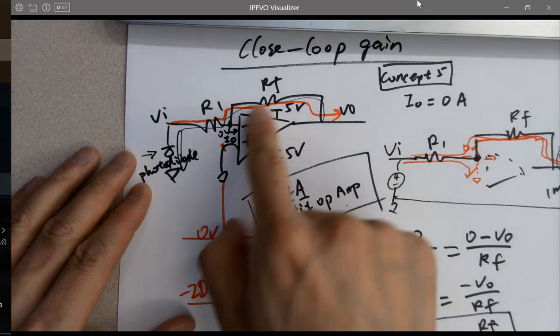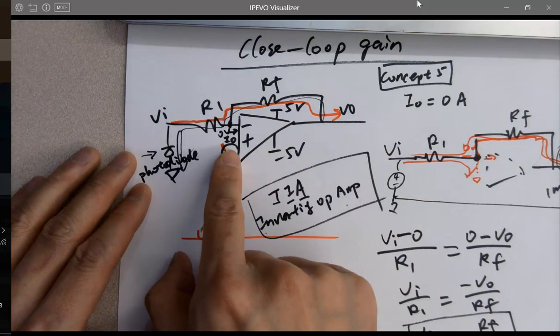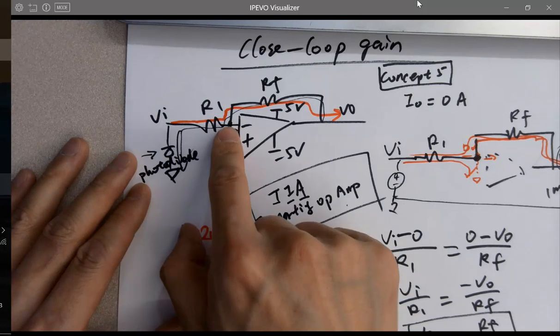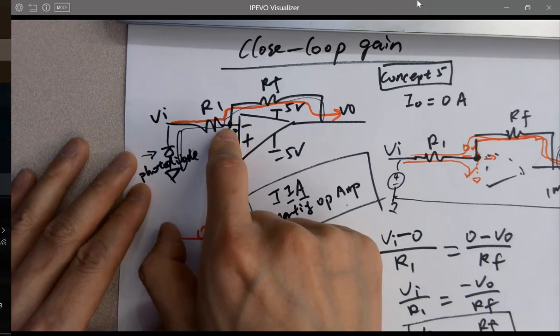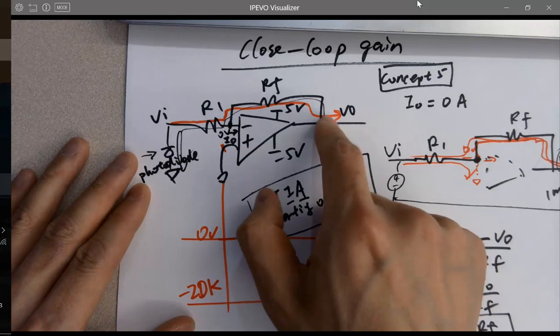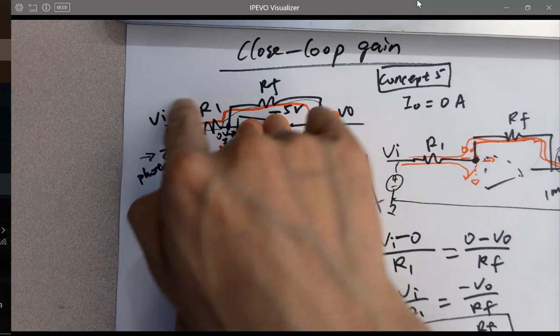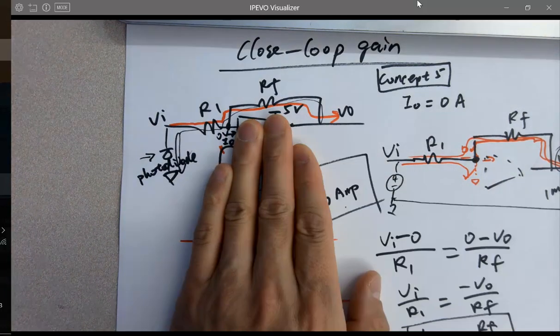You have this op-amp here because you are using the infinite open loop gain, and these two inputs are virtually shorted. That's why this point can be dropped sharply to 0 volts. That's how you get a gain. Because if you remove this one, you only have the resistor network. It's only dividing the voltage, not amplifying it at all.